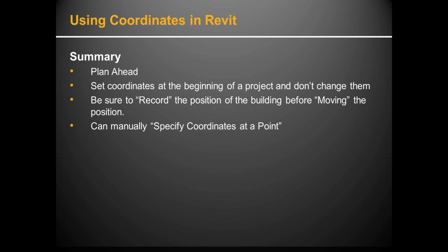I don't know if you're like me, where I'm in the residential field, the last thing I get is the survey right before I have to go for a permit. So I'm working off of made up, the best I can do site plan drawings, and I really don't have a bunch of time. But using the specified coordinates at a point will save you that time where you can just go in and realign things and get it done at that location. So it seems to be an easier way of doing it, and if you are having trouble with those things, using specify at a point is going to be a lifesaver.